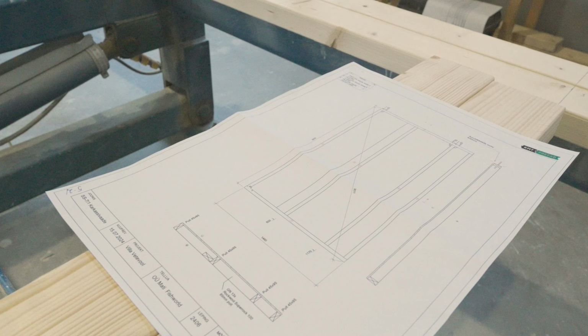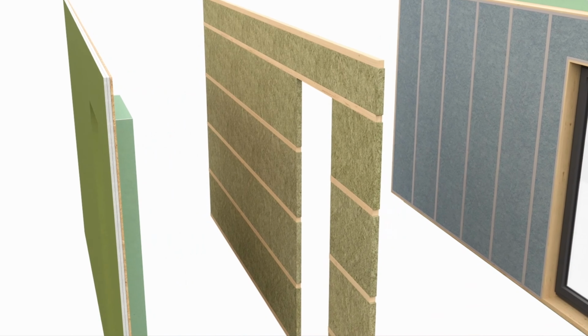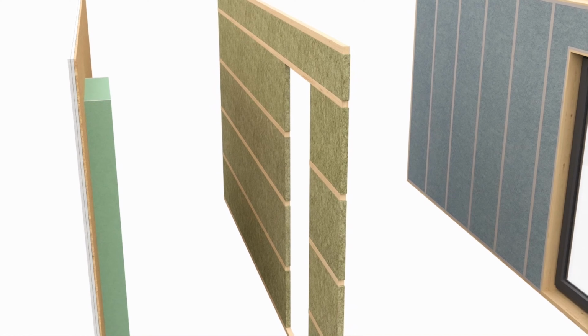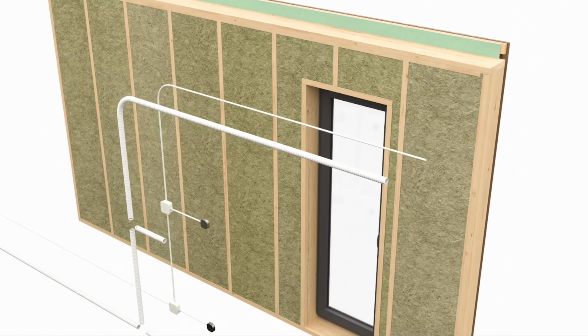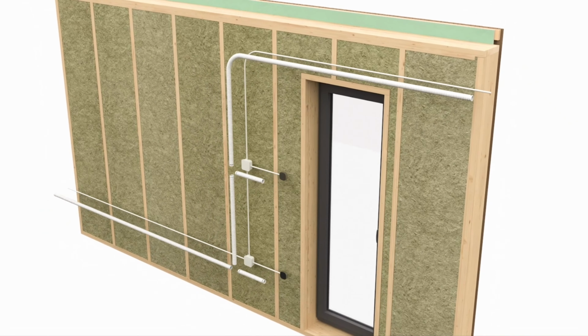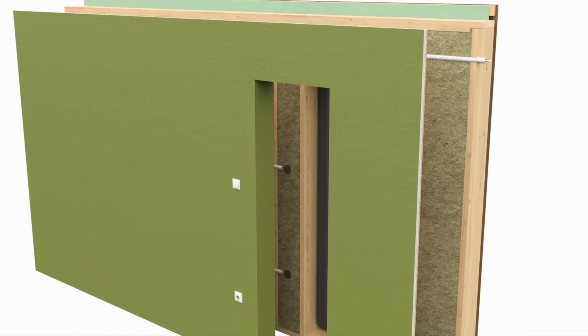Next, place the webbing on the work table and put the studs of the frame between the webbing in the marked positions, making sure that if the studs have holes drilled in them, they are on the right side. Usually the wall structure has an additional frame on the side of the room for the communications, but if it hasn't, then it is needed to drill the holes in the studs in designated places. As a rule, there are openings on the inner room side of the studs.